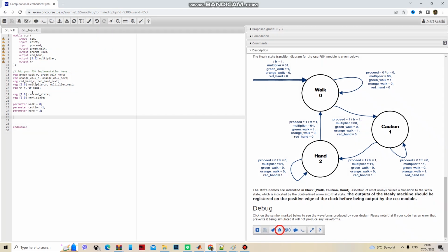Okay, now we want to continue further down. Always at posedge clock begin, and if reset begin and else begin, and now here we want to reset all of these variables, right? So all the synchronous variables should be reset. It's only the Rs. I keep calling them variables, but they're registers. Don't mix those two.